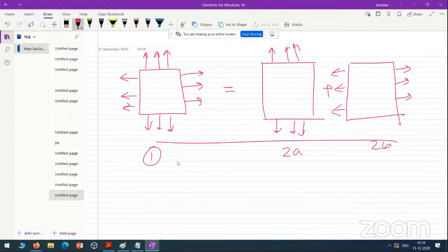If you are within the linear zone, you can take the individual forces one at a time, do the analysis, and then superimpose them to get the total response. So this is how linear superposition is applicable. But remember, this is only valid when you are talking about linearity.